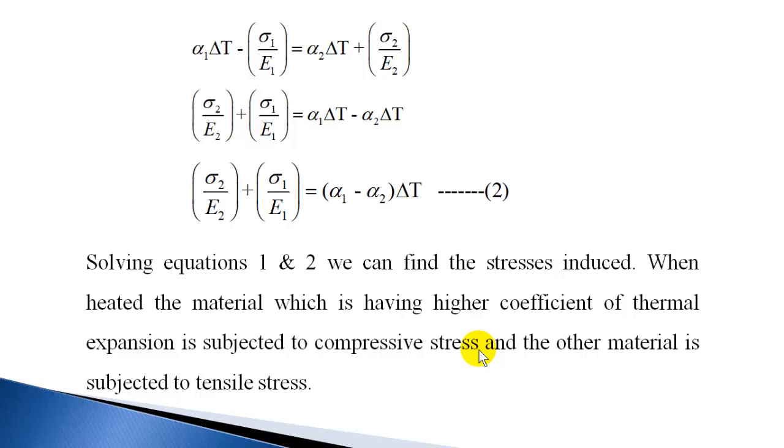Whereas when it is cooled, the material which is having higher coefficient of linear expansion will try to contract more, then the other material has to exert a pull or tensile force to reduce this contraction, and the other material will be subjected to compressive force.